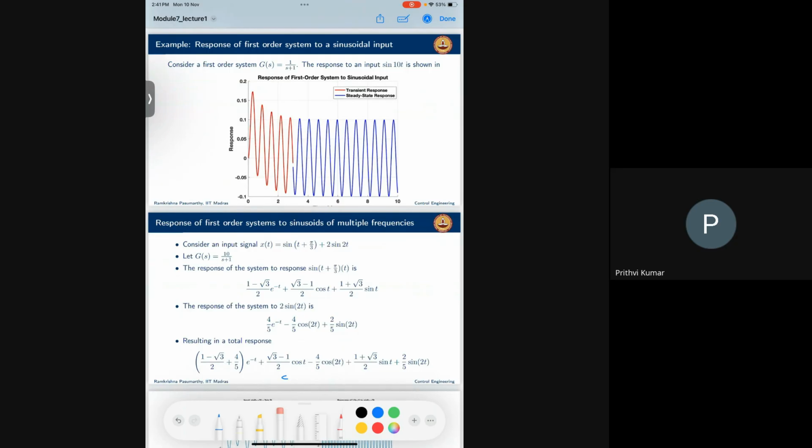Why is it useful? Any idea? Why is frequency response useful based on the things I have said before? You don't need any model of the system. The important point is that you don't need any model of the system. If you have a black box system, black box means you don't have much idea or knowledge about the system. You give it one input and get some output, and based on this input and output and very little knowledge of the system, for example, whether the system is linear or non-linear, based on the output itself we can say if the system is linear or non-linear.